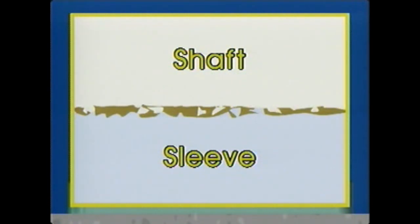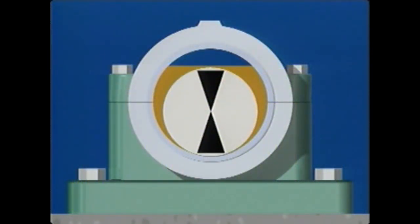Part of the load is relieved by the lubricant, but the high points of the mating surfaces take most of the load, which results in friction and wear of the surfaces. Mixed film lubrication is by no means an ideal situation, but it is a common occurrence. A third level of lubrication is film lubrication, also called full film lubrication. It occurs when moving and stationary surfaces are separated by a film of oil.